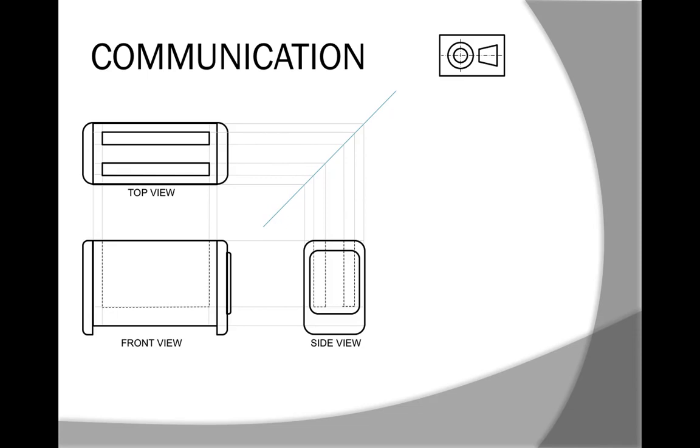Let's have a look at my marking guidelines. They asked for 6 marks, right? If they ask for 6 marks, draw this symbol. All right, it's a lot of marks for this question. It's a pretty simple question. So draw that symbol, the third angle projection symbol. Okay. The shape. Does it basically look like a toaster? Yeah? Okay. Dimension transfer. That means, I call that alignment these days, right? Do these shapes match up? Does this shape line up with that shape? Yeah? Okay. Did I label it? Yeah? Top view, front view, side view.